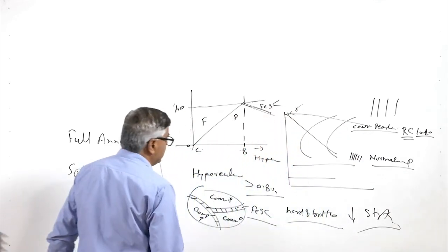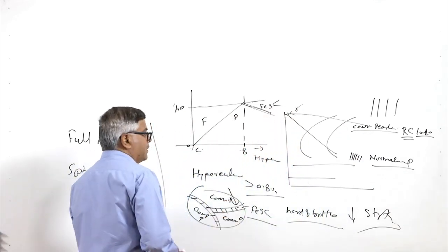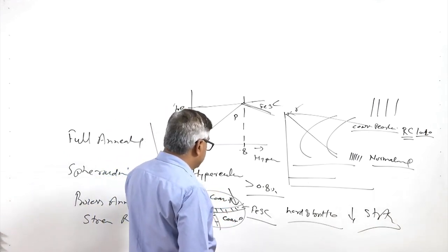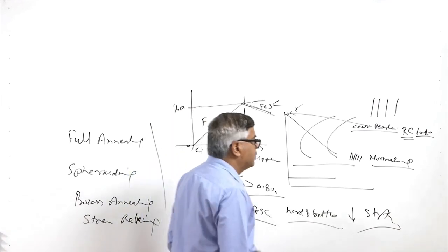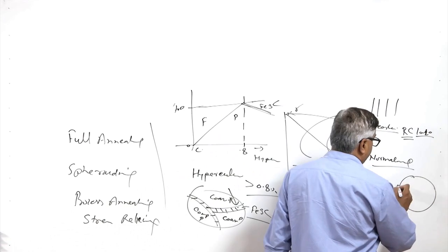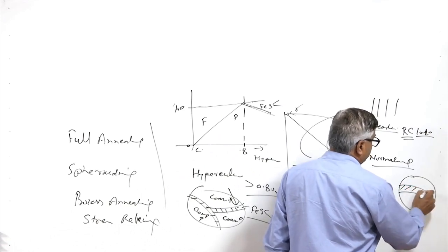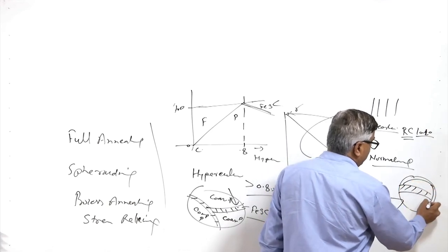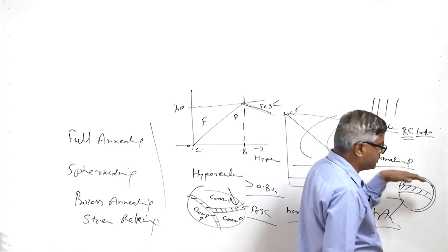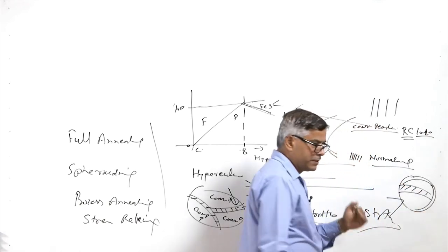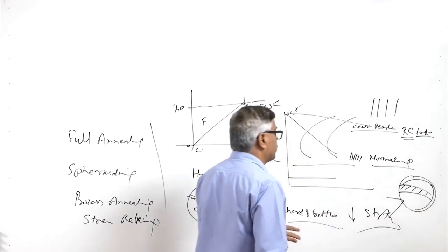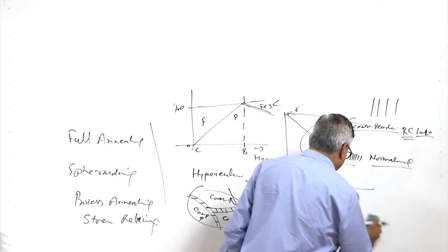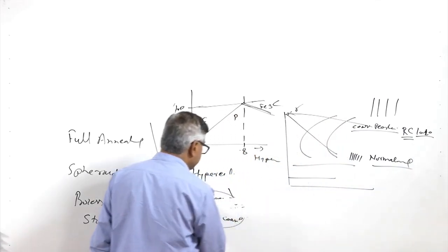Further, during machining, such thick layers cause interrupted, irregular shock loading onto the cutting tool. If the thick layer of cementite is present during machining, then the soft metal will be easily machined, but as soon as the tool comes across the thick layer of cementite, which is very hard and brittle, it causes shock loading onto the tool. So, that may lead to fracture of the cutting edge. This factor basically reduces the machinability of the steels.